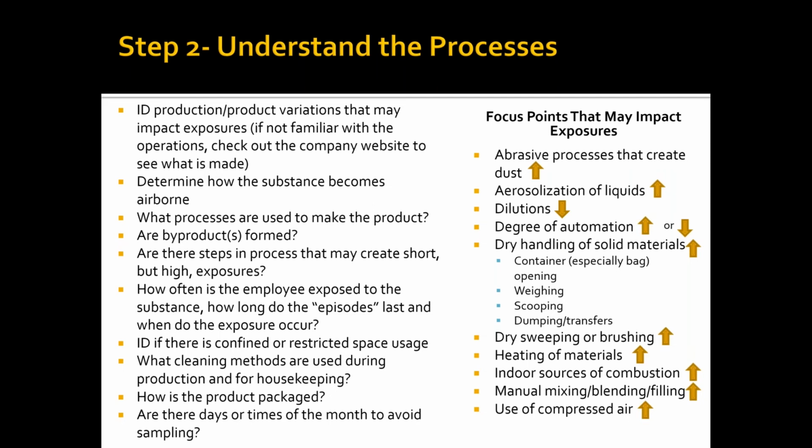How long do the exposures last? Are they periodic? Do they occur all shift? Are things used in a confined or poorly ventilated space? What do they use to clean up things? All of this is information that I like to know up front because I think it helps me do a better job of planning for the survey and helping people out by identifying exposures that maybe they hadn't really thought about before. Oftentimes this whole question process gets to be kind of annoying because it's like, wow, that's way too much information here, but it'll help everybody do a much better job.